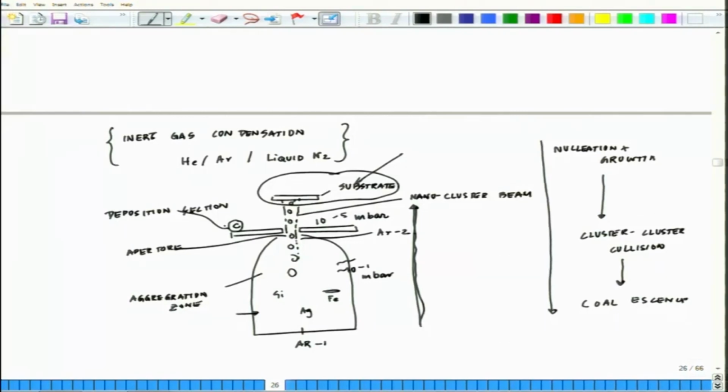So, the way it works is very simple. Electron beam hits the target material. The target material atoms evaporate when temperature reaches above its boiling point, and evaporated material is then transported and condensed on the substrate, and the advantage is again high deposition rate and can be used to deposit material ranging from conducting to insulating. And unlike thermal evaporation, electron beam evaporation can be used to deposit material of high boiling point.